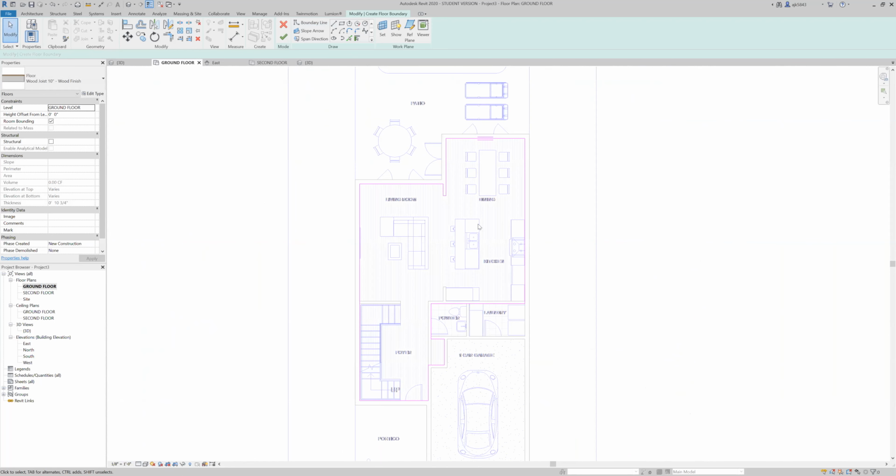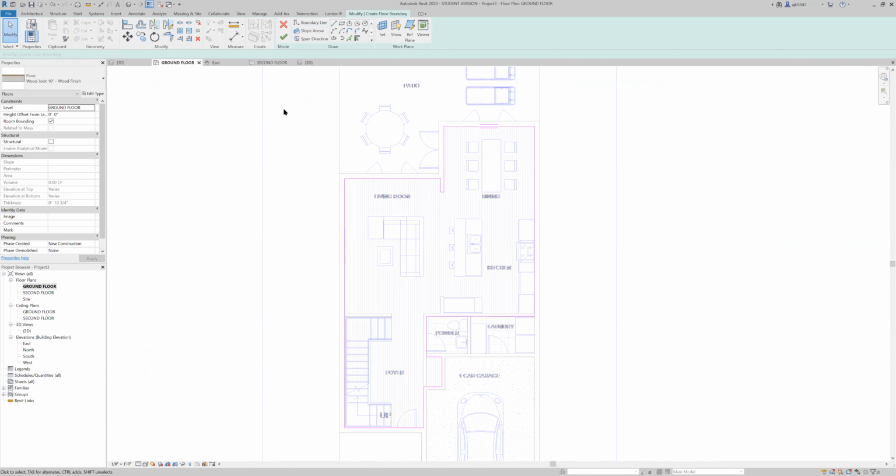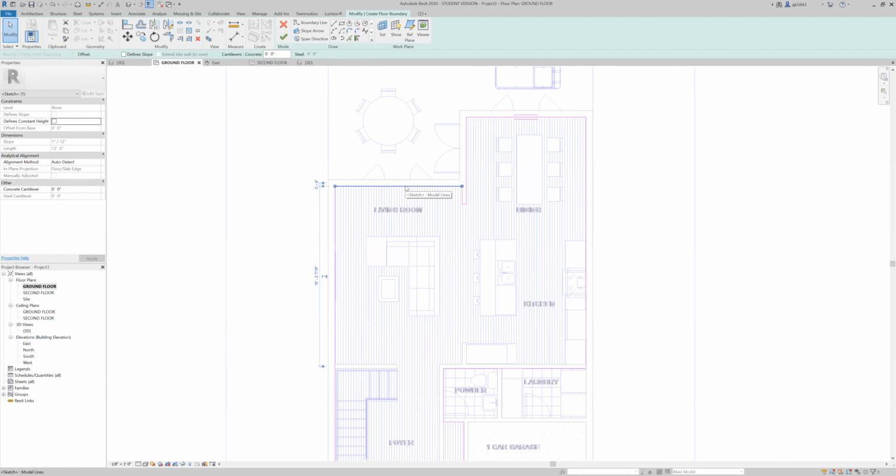I think we're looking good there. We have a completed line. That is the one thing about sketch mode that I don't believe we mentioned. If you do not have a full and closed loop, it will not let you finish the sketch. Maybe just delete one of the lines.